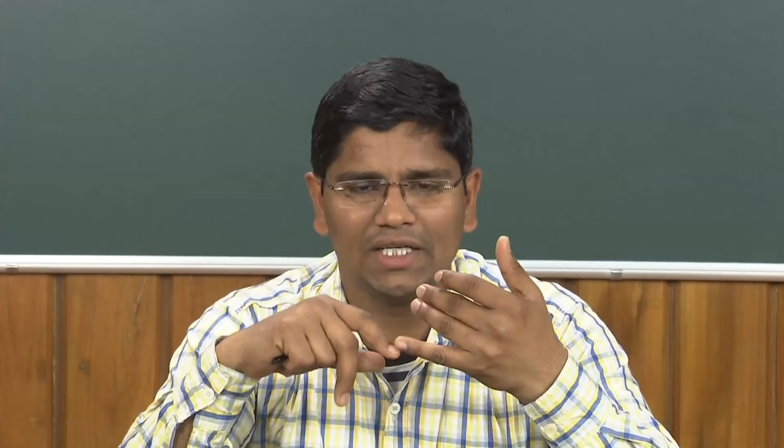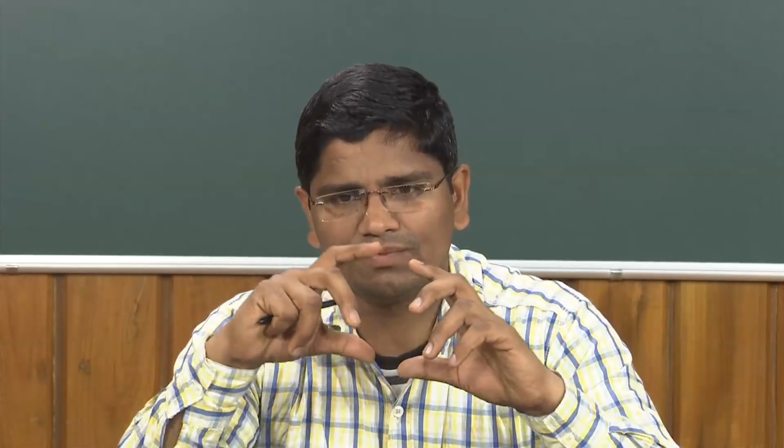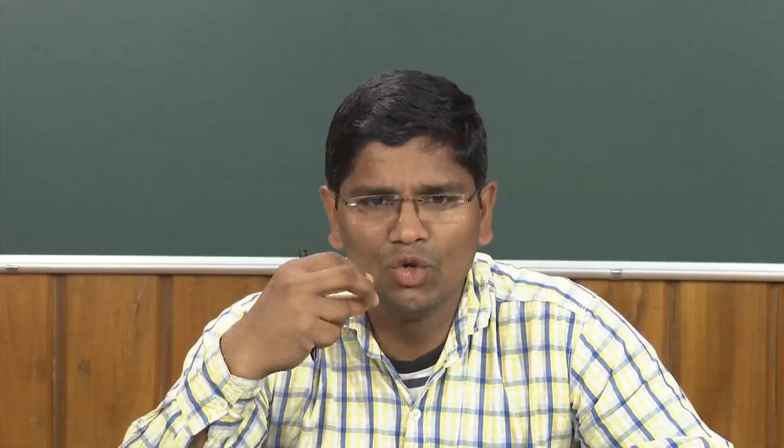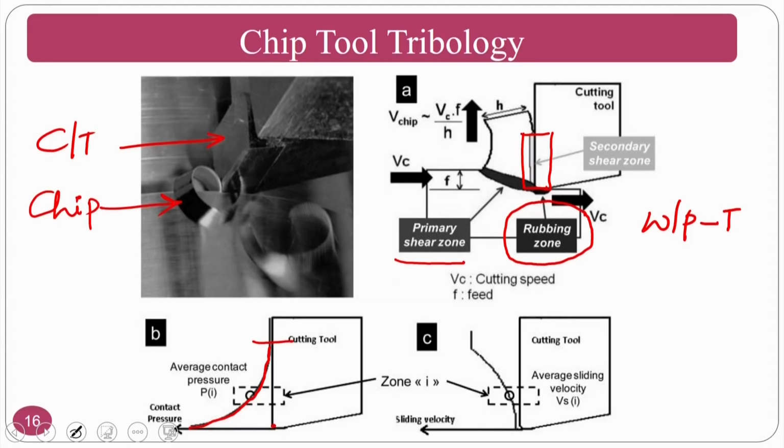Okay. So for that purpose, always try to avoid this by using cutting fluid or tool coatings or something. Normally, if you have given a relief angle or a flank angle properly, that itself is a good thing against the rubbing action on the workpiece. I mean the final product that is coming out. Okay, if you can provide a lubricant jet across the workpiece and tool interface, that will also help the workpiece and tool flank surface interface.